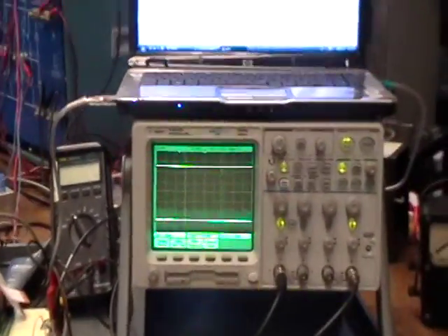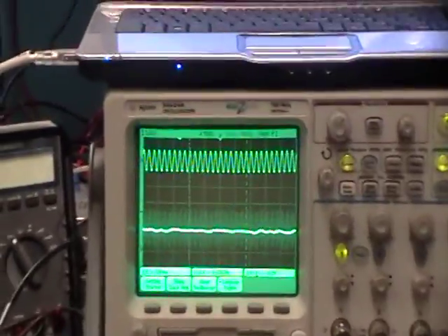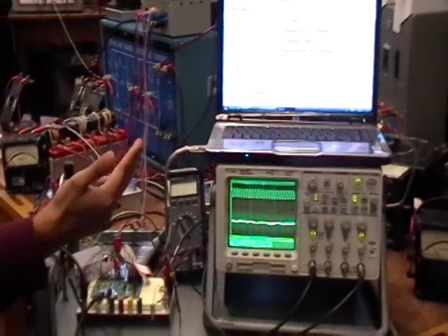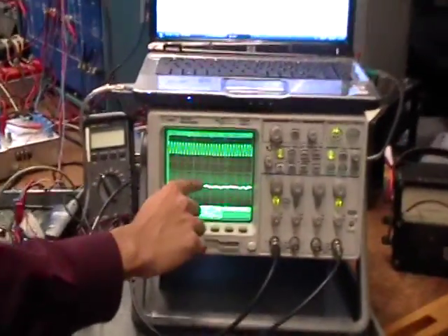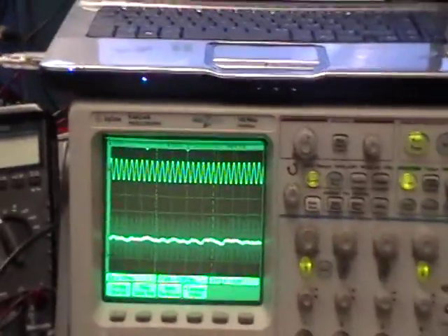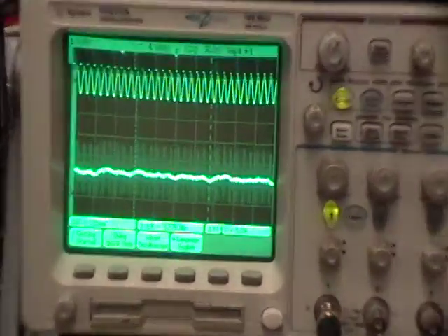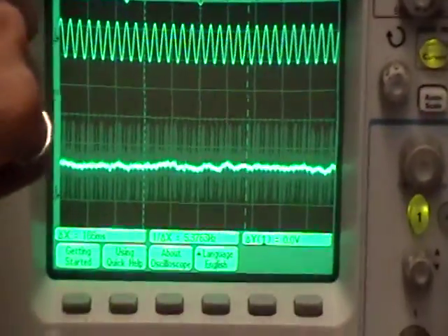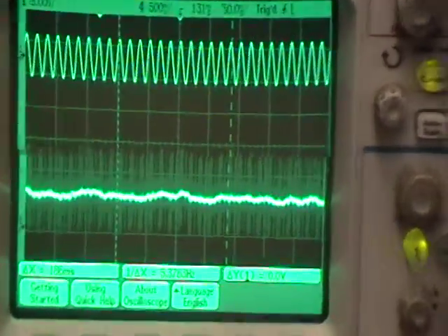Matthias? So right now nothing's happening, but we are supplying power as well as injecting the negative sequence signal. If you look here, this curve represents the negative sequence signal that we're measuring right now with the injection included. That's the signal that's going to increase when we trip off the generator.